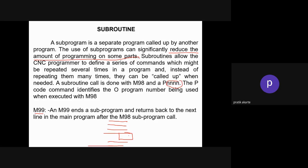So this many subprograms you can include in your main program. Now if you consider that this subprogram has 10 blocks, instead of writing 10 blocks every time, you can call this subprogram. You can form the subroutine and call it as and when needed. So the length of the program will be drastically reduced, and the program will save time. So that is the function of a subroutine.